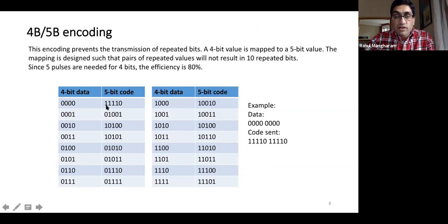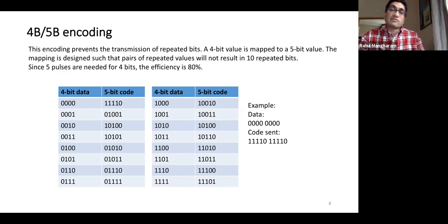Because whenever I have a 1, transition, no transition. So here I basically had no transition, and here I have a lot of transitions. So I map whatever I have to a larger number of bits, from 4 to 5 bits or from 4 to 8 bits. And therefore I'm forcing the number of transitions because I'm going to map it to a sequence that has, by default, at least that much or more transitions than the original signal, right? Because transitions are actually communicating that information.